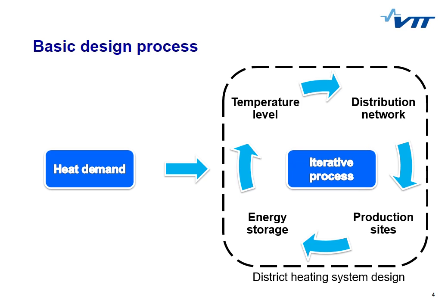While consumer heat demand remains the same, there are a lot of dependencies between alternative design choices, for example between temperature level and production output. In the end, feasibility of a system is assessed in a techno-economic analysis. Other alternatives also exist, such as share of renewables in production or self-sufficiency. Usually, the final decision on the design is made based on several key indicators and greatly depends on the system in question.